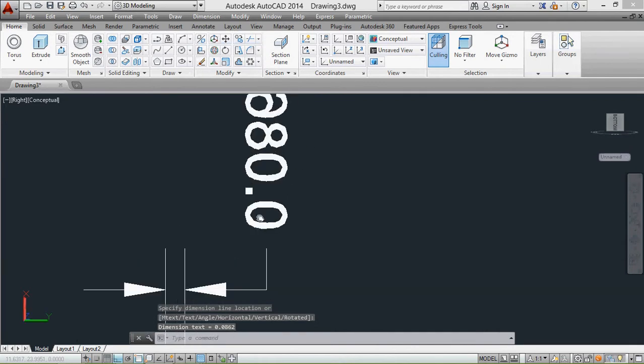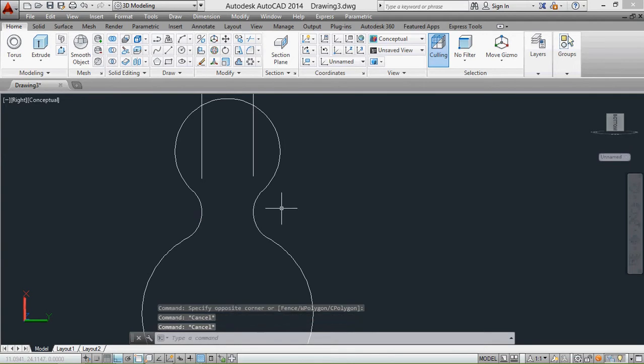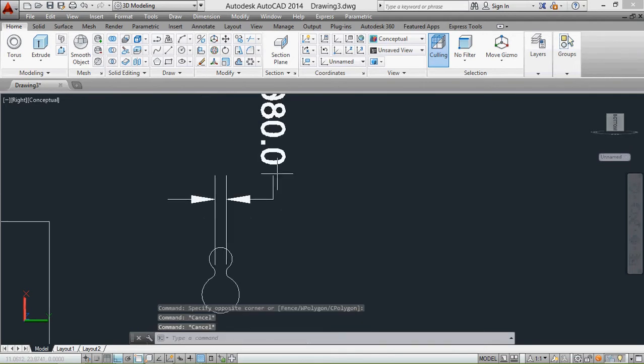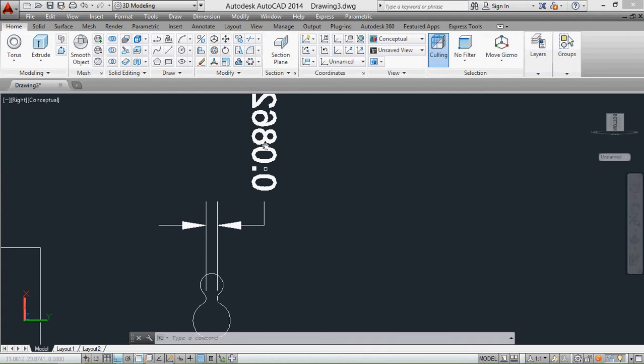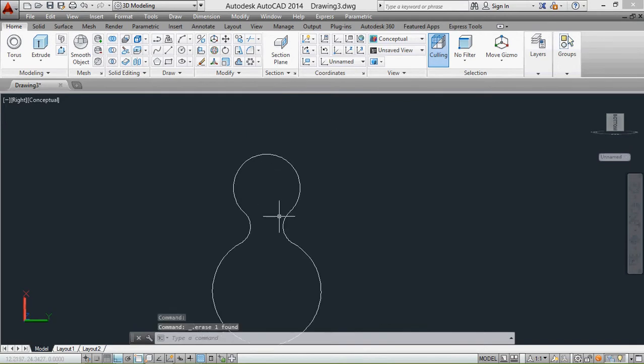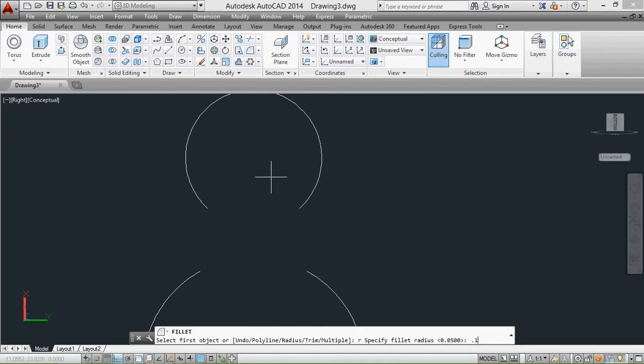So actually that's too small. So you gotta play around till you get the perfect size. Oh, that's the radius. Sorry. It's 0.16 right now. If I double that number, and I'm looking for 0.17, I gotta make that a little bit bigger. So I had 0.10 for the radius for the fillet. I change it to radius 0.11, and that should be enough.